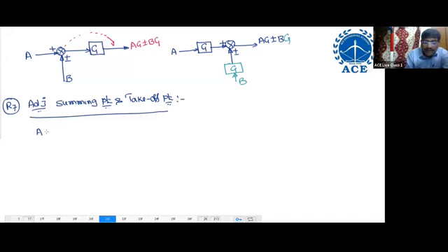For example, here A, here plus R minus B, here take-up point. Now shift this take-up point ahead of the summing point and draw the output. Actually, this last rule is not required, but still you should know.